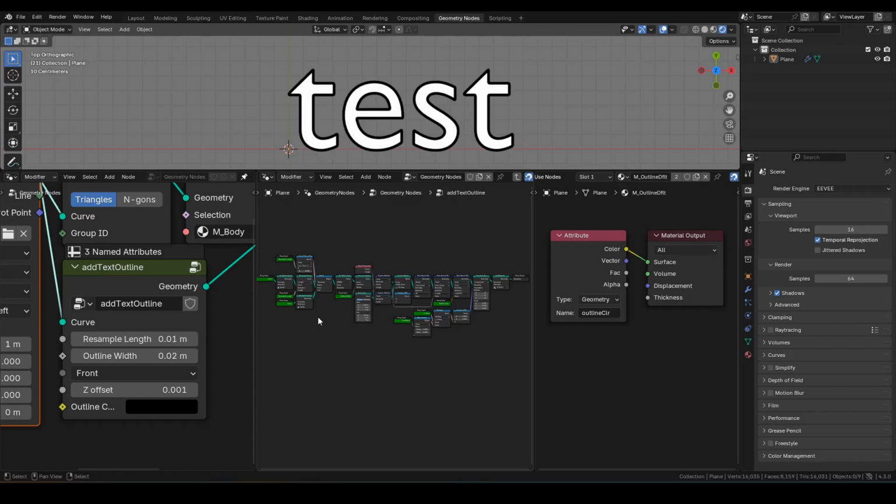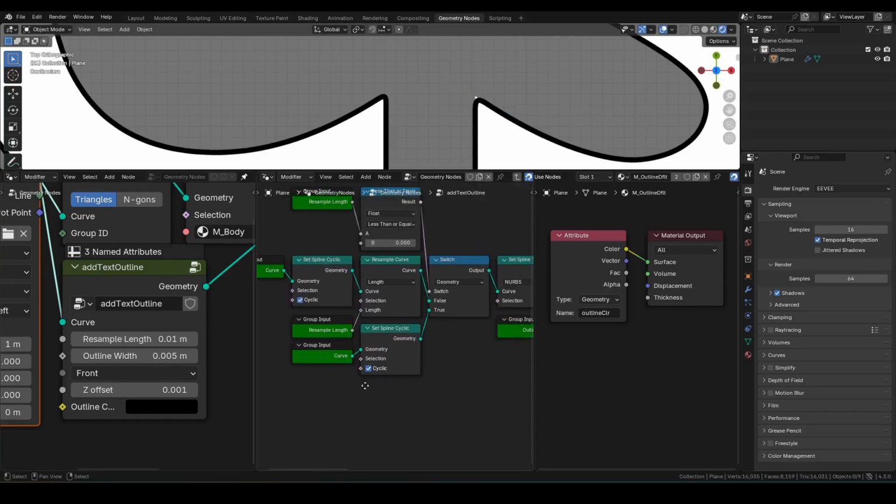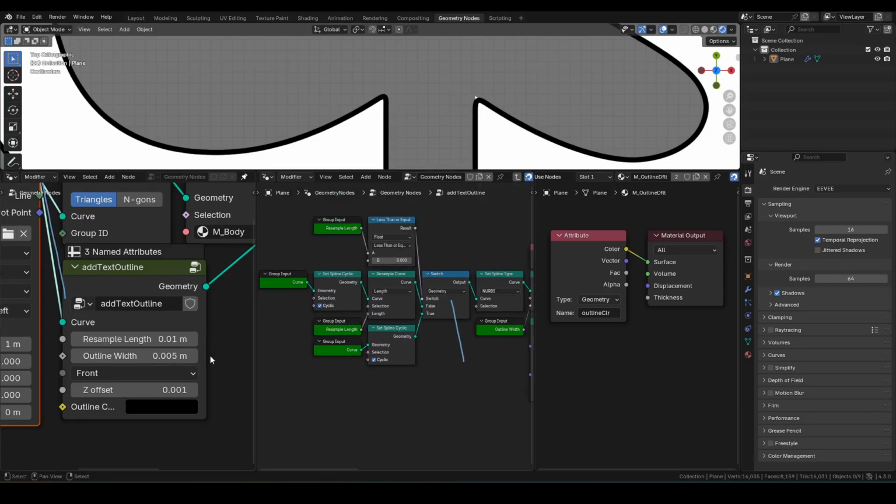If I choose to go for a more narrow and sharp look, there is a slight issue if I simply decrease the line width. Let's try decreasing the width to 0.005 meters. As you can see, with a beveled outline, we have this fill corner protruding out. This switch condition prevents beveling by setting render length to 0, so I can retain the sharp corners.